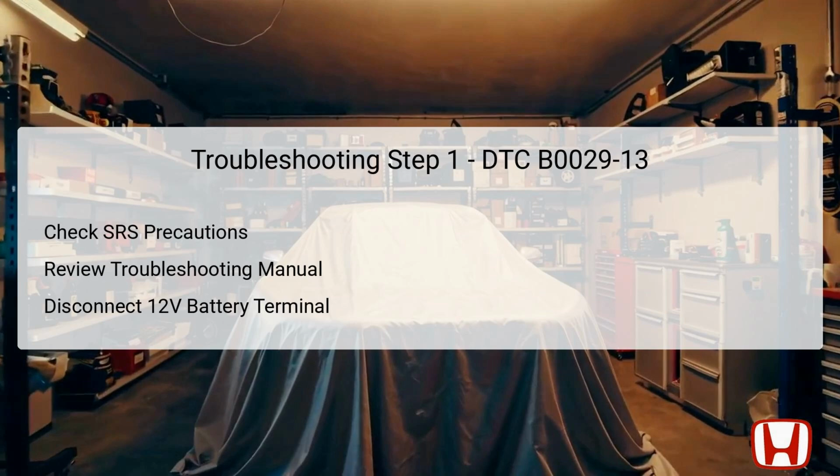Finally, before handling any SRS-connected components, you must disconnect the 12-volt battery terminal and wait for at least 3 minutes to ensure that all stored energy in the SRS unit has been discharged, minimizing the risk of accidental deployment.